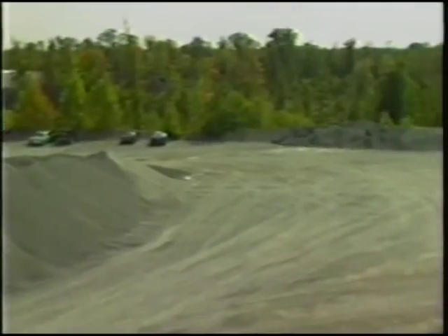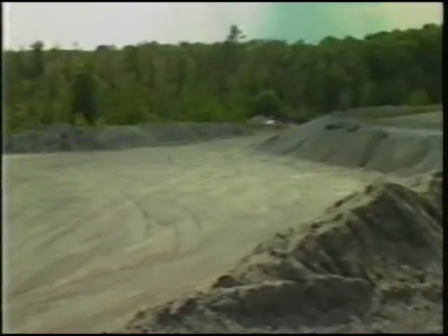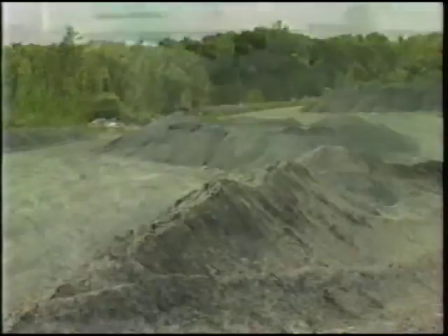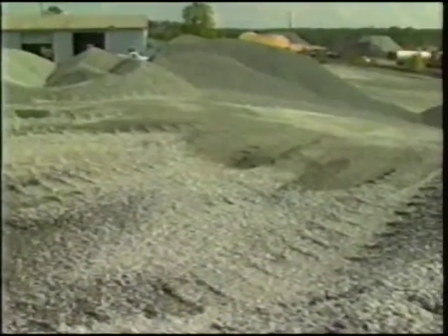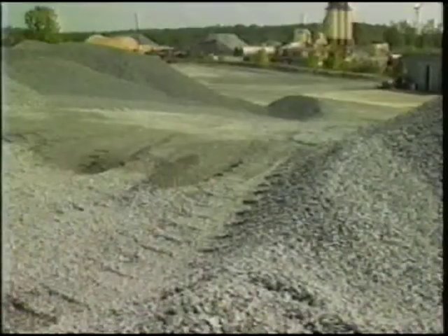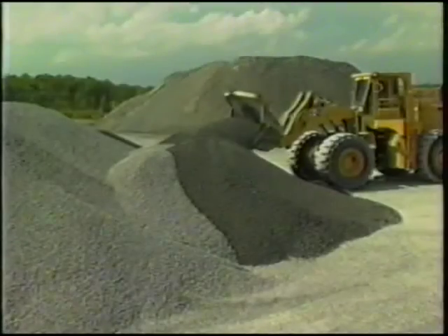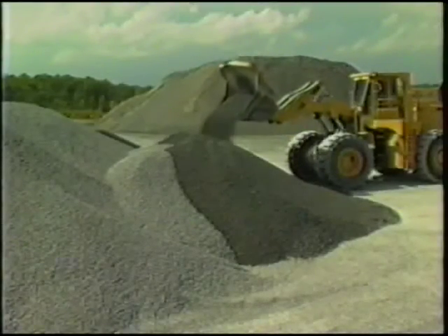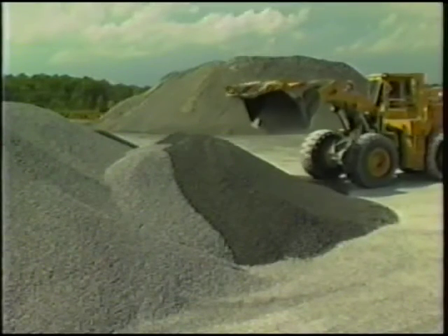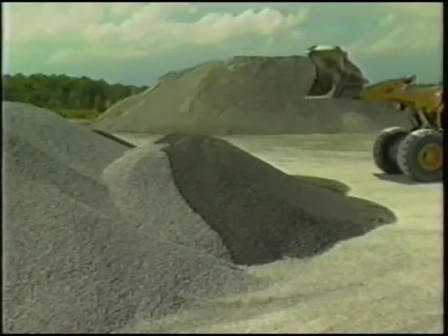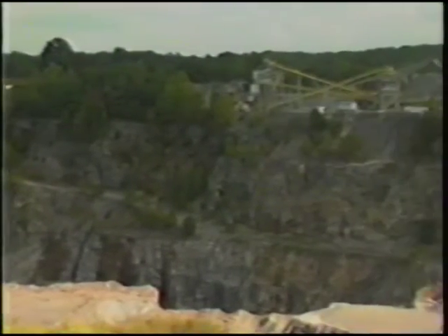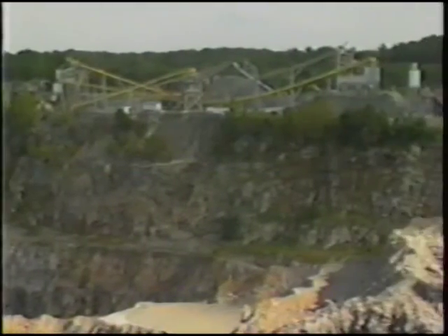At this plant, the stockpile is on a clean and level surface, and different aggregate products are well separated. At this plant, the stockpile is not as well maintained. You can see in this level that the product has been crushed. Attention to the details of handling aggregate material should result in a product that is clean, not segregated, and meets specifications. Keep in mind that changes in the quarrying operation can cause a detrimental change to the final product.